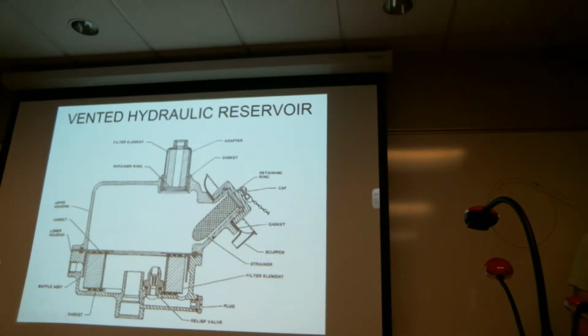So we have a bypass valve installed too. They label it as a relief valve. In the event that the filter becomes clogged, the dirty fluid can bypass the element, and we will be able to get fluid to the pump anyway. And by the way, you'll really never know that the bypass valve is open and you've got dirty fluid, because there's really no differential pressure indicator in that type of filter. You won't notice anything, but you will get fluid to the pump.